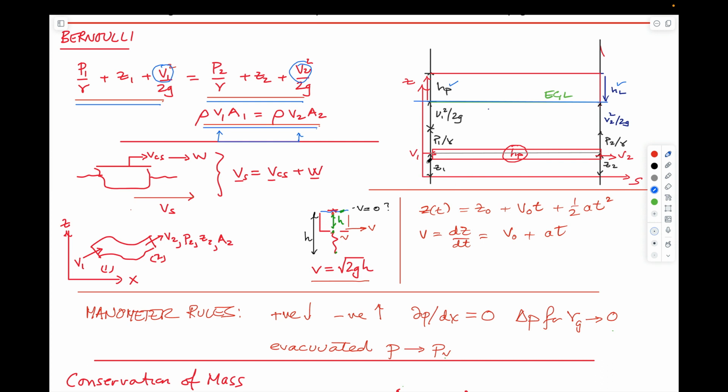Physically, the 3 components of Bernoulli represent an elevation of the location of the pipe, the pressure that location feels, and a velocity head, which is represented by the velocity along here. If the pipe cross-sectional area is constant, then these 2 velocity heads have to be equivalent to each other, and therefore we can scale the magnitudes of the pressure from that.